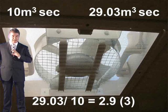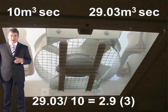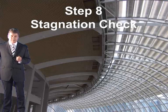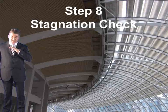So that's all we need. We don't have to take one out in a fire. We need 3 fans located symmetrically down the reservoir. So that's how many actual ventilators we need. That covers step 7. Now we can move on to step 8, which is the stagnation check. Because this is a mechanical system, the stagnation check does not apply. It only applies to natural systems. So again, we can kick this step out.